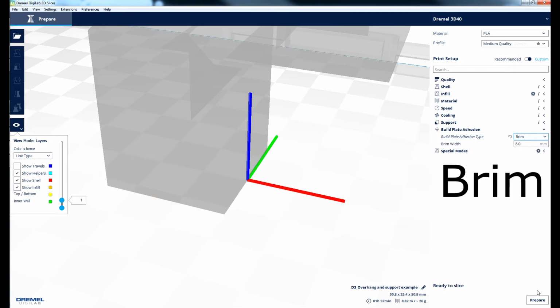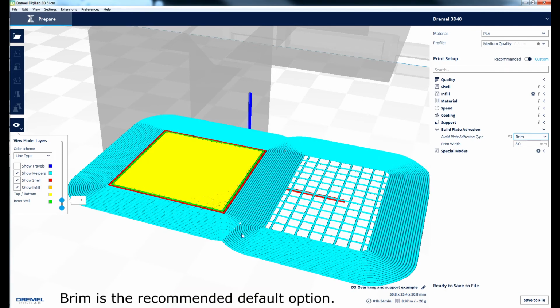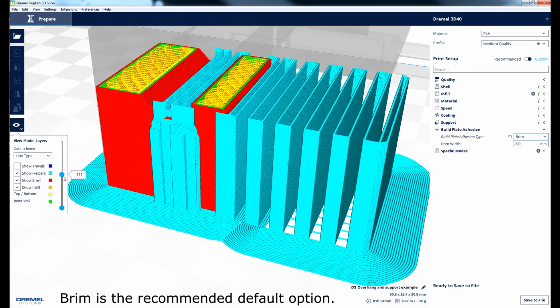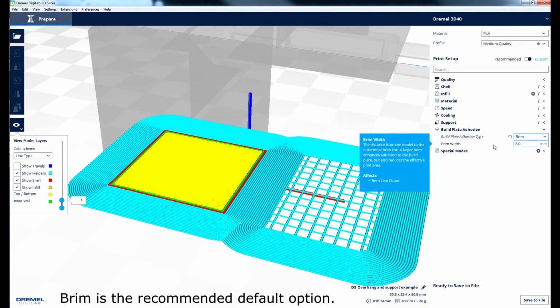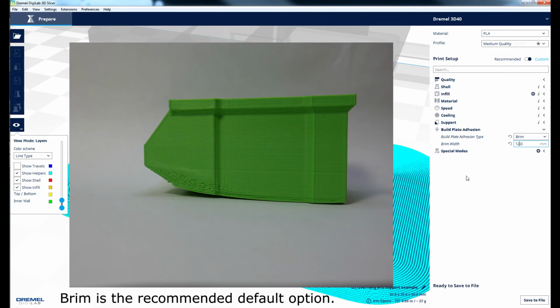Brim. Brim expands the silhouette of whatever is touching the build plate, creating a larger surface area for your print to stick. The brim is always printed with concentric extrusion rings, making the brim layer peel off from your part with ease. Parts with relatively small surface area in contact with the build plate will benefit from using the brim. Large parts with corners that are susceptible to lifting or warping from the build plate can benefit from using brim also.